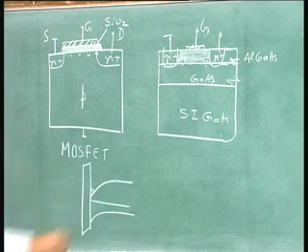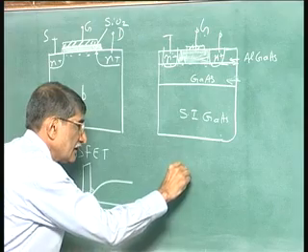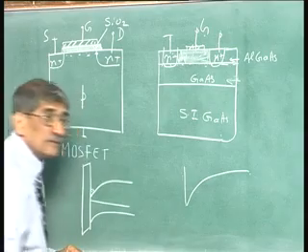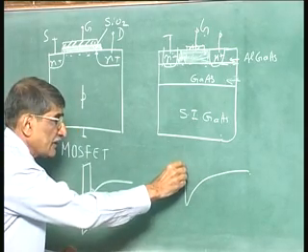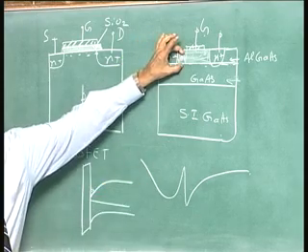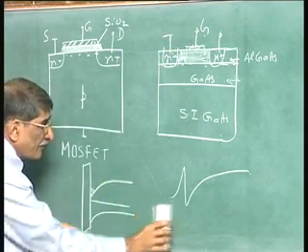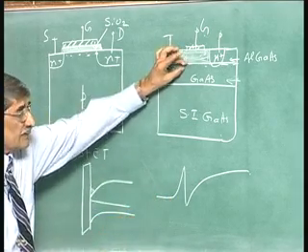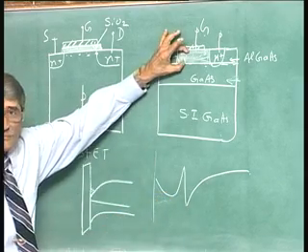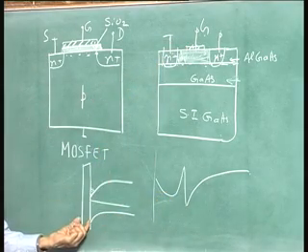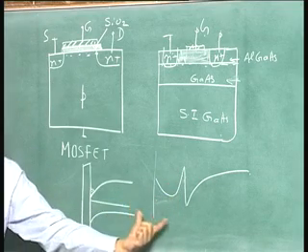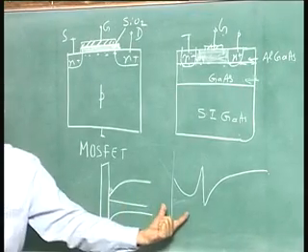Okay. Here what you have is a similar notch in the conduction band. I am plotting only this one here, that is the conduction band notch, and from there onwards, what is this? This is the depleted layer. If it is not depleted, it will go like that, a thin depletion layer, but when you apply voltage, it will go up like that. So, the entire layer is depleted here. Here it is oxide. So, replace this with that. I have shown it thicker here just to enable me to draw this diagram. This can be thick or as thin or even thinner than that.